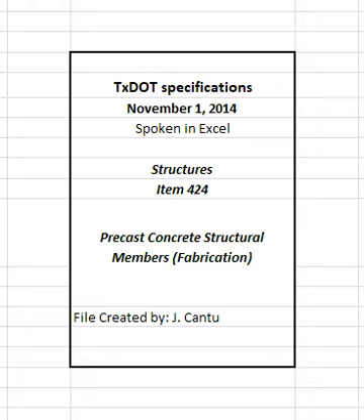All cores from precast members must meet 100% of the minimum design compressive strength requirements. For concrete that has been determined to be structurally adequate, coring of the in-situ concrete will not be allowed for the purpose of avoiding the price adjustment. The department may require reimbursement for testing of cores. Testing by an approved commercial testing laboratory will be at the contractor's expense. Test results from a commercial laboratory must be sealed by a licensed professional engineer.